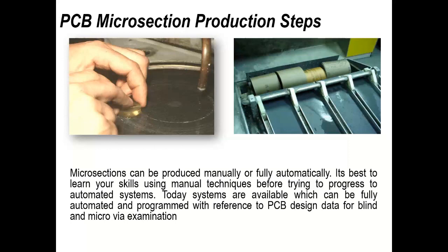When you're doing it manually, what you're trying to do is keep a flat sample, a flat face, but you might be trying to take a little bit more material off the back or the front to even up the sample, to get to the area of interest. And that's why you're holding in this sort of way, and you're applying pressure possibly on the front or the back or the middle, depending on where you are in the sample. Of course, if you're doing this automatically, then this is sometimes taken care for you.